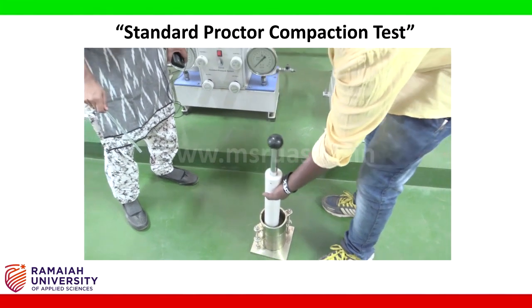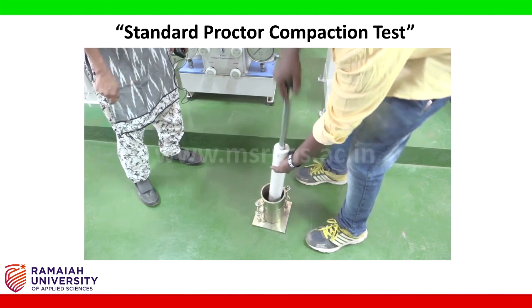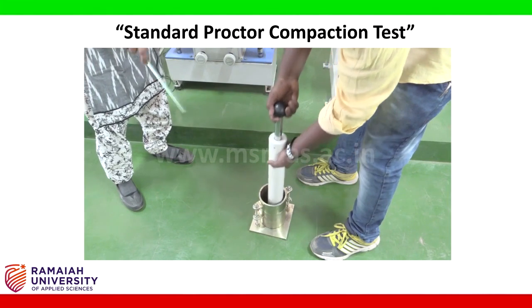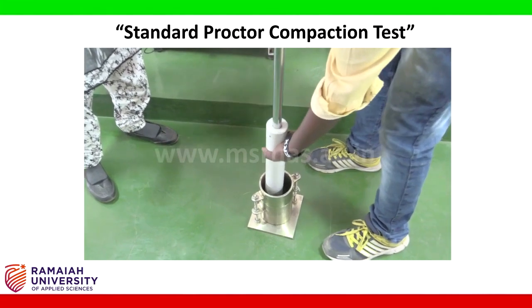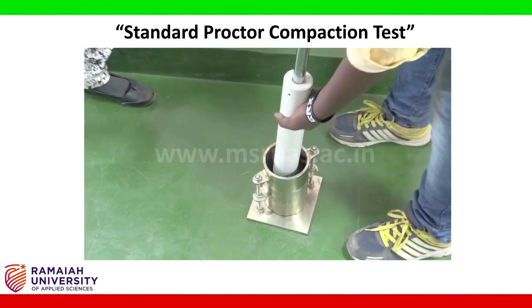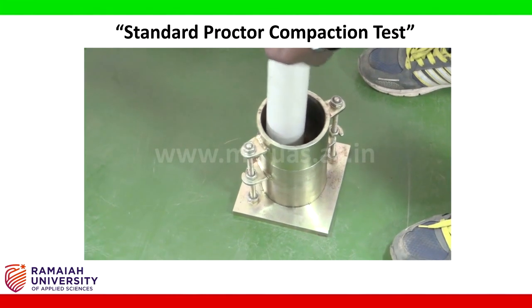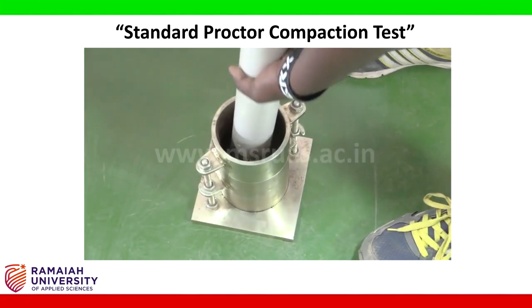Ram it for 25 times, and the blows should be evenly distributed. You have to rotate the rammer. As you progress, count the number of blows also.